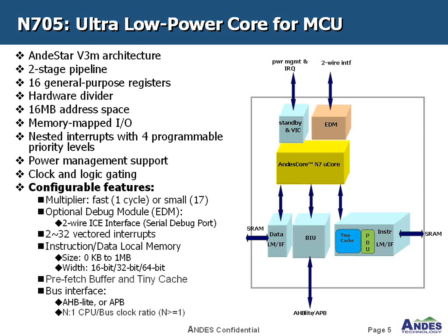For the bus interface, N7 can choose AHB Lite or APB, and can choose different clock ratios between the CPU and bus. It can help users reduce SoC power consumption.